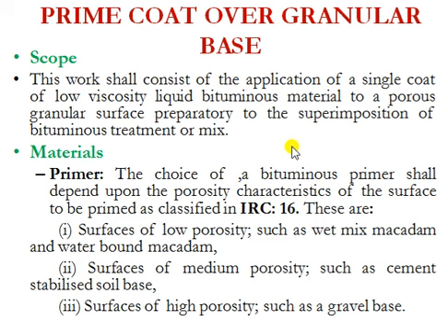The prime coat is typically a low viscosity bitumen application over a granular base. So the application of this prime coat is to prepare the surface for laying of a bituminous mix or for the laying of asphalt mixture.